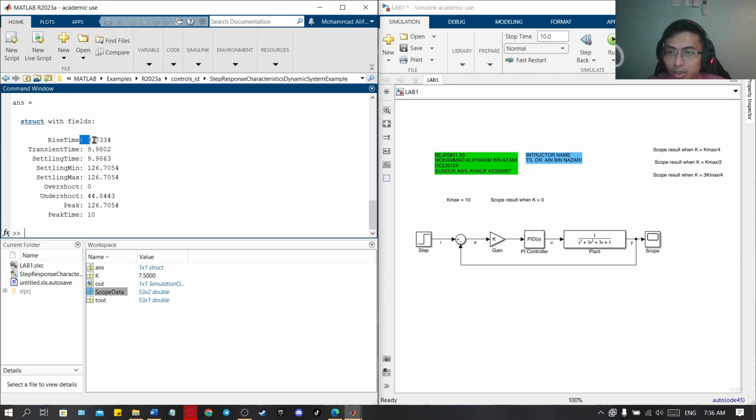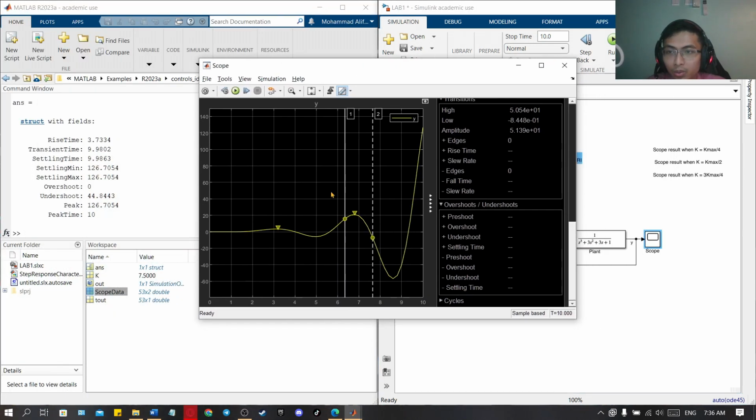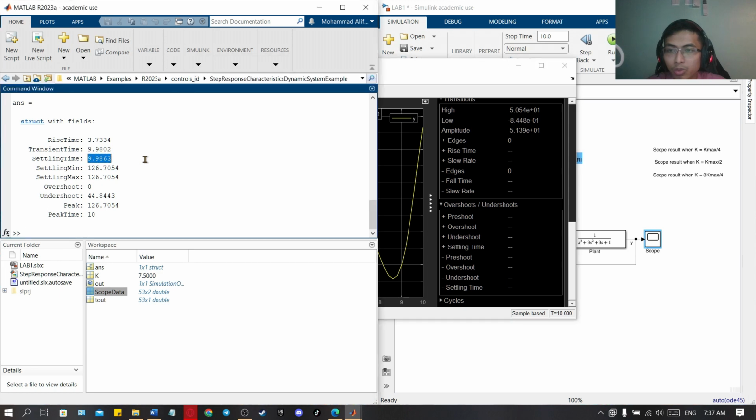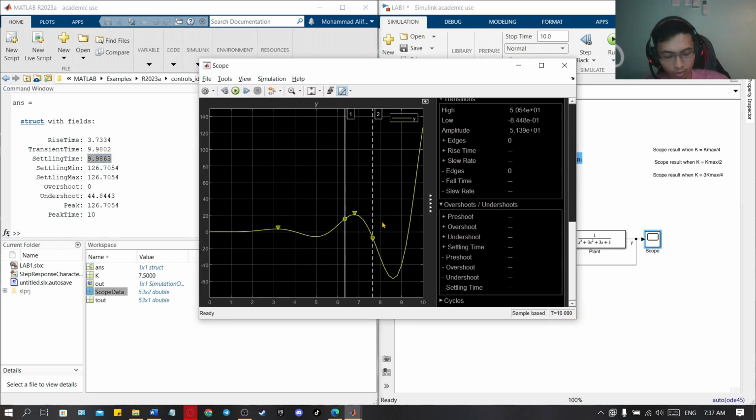We show the rise time, the settling time, and the overshoot. That is one. We can refer to it here because in the scope graph it doesn't have any peak, so the overshoot will become 0. And the settling time, we can take it from the graph. I believe rise time is obtained by subtracting 10% of the final value from 90% of the final value. So from here, maybe here, and the settling time is right before the graph becomes stable and linear.